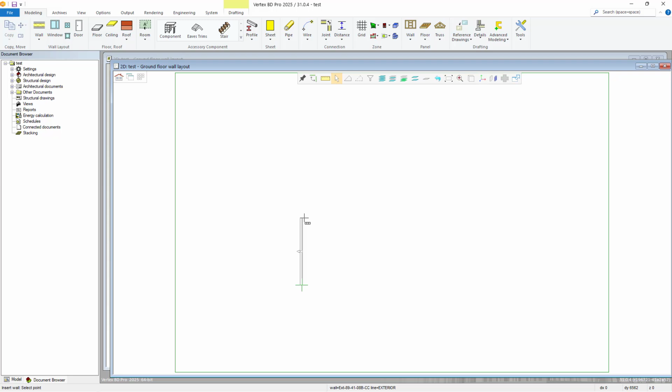As we require a 4 meter by 8 meter model and are constrained in the vertical direction, we can start typing 4000 and the distance window will appear automatically. Once the correct figure is entered, hit enter on the keyboard. We can then repeat this horizontally by hitting U on the keyboard and entering 8000 and hitting enter. Again, I hit I to lock vertically and type 4000, then locking the x-axis again with U and return to the origin point, clicking when we see the yellow dot.